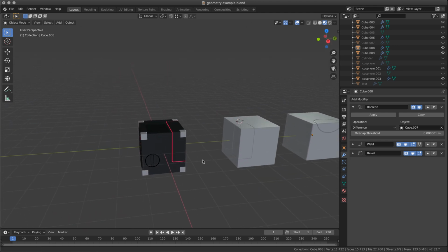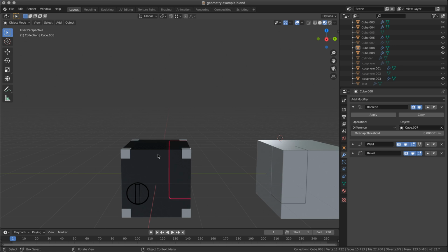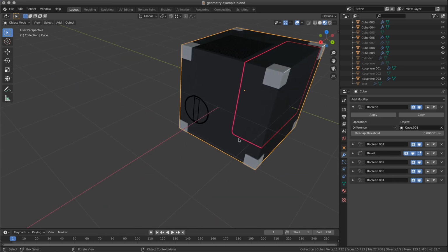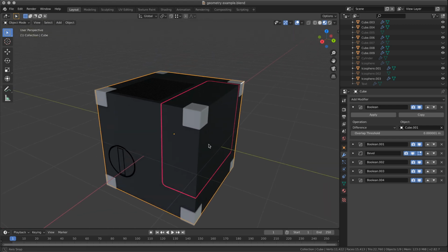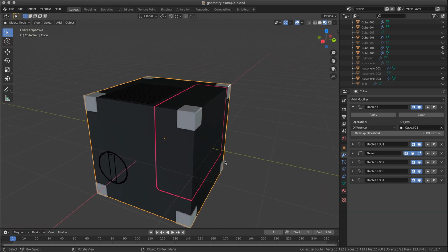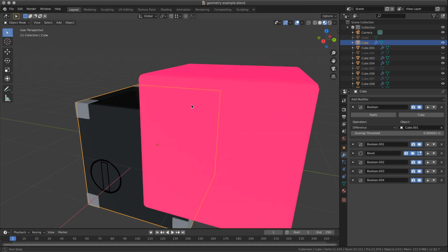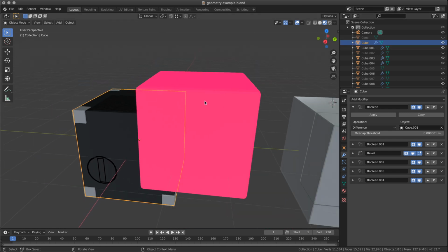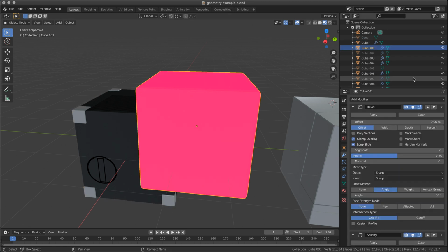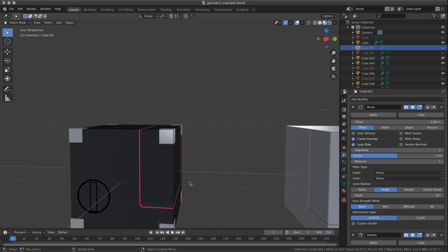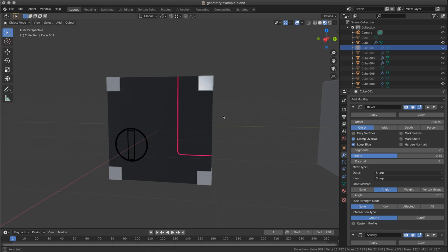Another thing that I want to show that is very cool when you use the Solidify technique, which is what I used here. I started with 2 cubes, and let me show the second one. So I had this cube that I used to cut the first one. Let me hide that. I'll select it and I'll hide it. And as you can see, I started with the bevel on that cube.